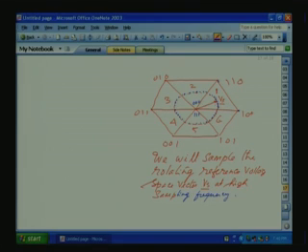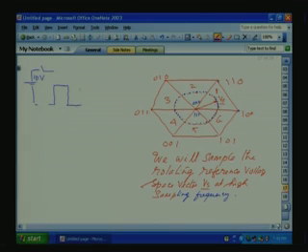Let us take, we have a 10 volt DC. This is our 10 volt. Now I want 5 volt. So what I will do? I will chop this waveform. 5 volt means for 50% duration I will make it on using a switch at the output where the voltage is required. Then for the next 50% it will be 0. So it will go like this. This is the T on period, this is the T off period. And we want 5 volt average value.